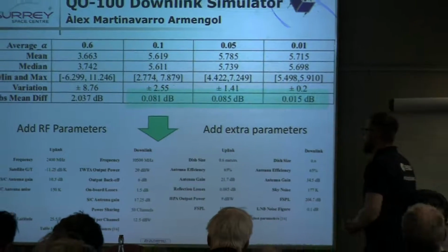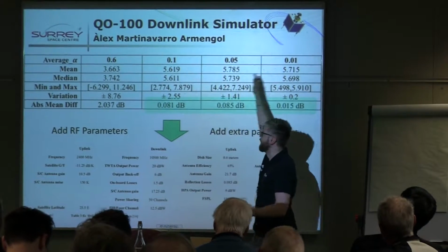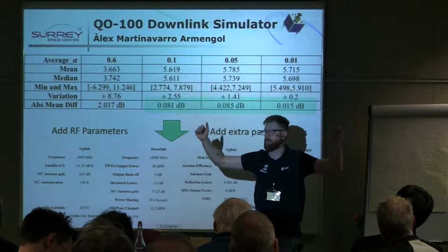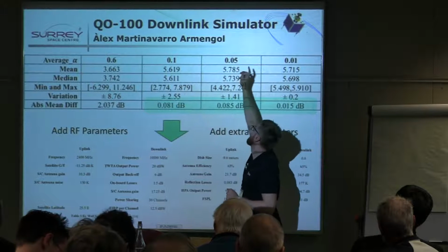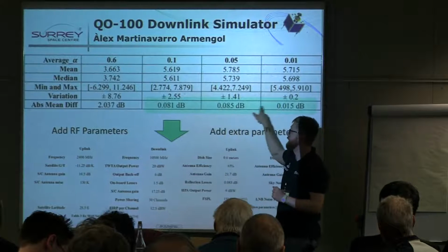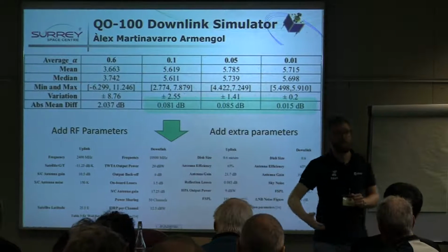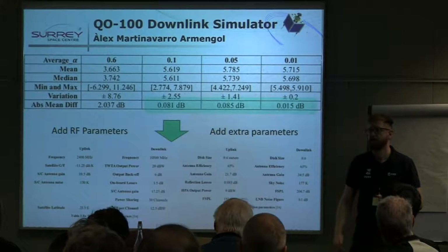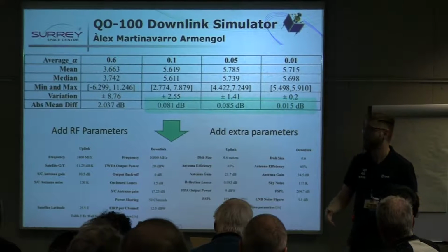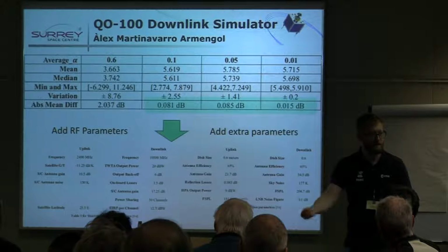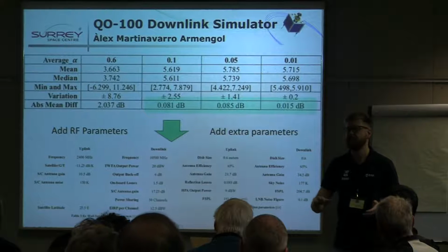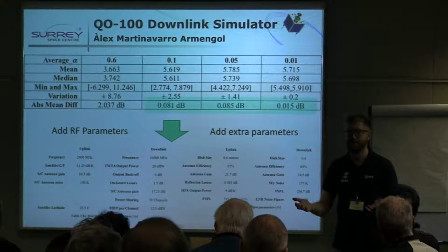Well, if we have certain levels of alpha, 0.6 alpha is just a massive filter. You're taking in essentially too much. But for 0.1 and anything less than that, we're within fractions of a dB of the original signal that we want for theory. Okay, good first steps. He's done a small experiment. He's actually gone through, made predictions. He can relate it back to the theory. What we've done here is essentially skipped 90% of the equations.